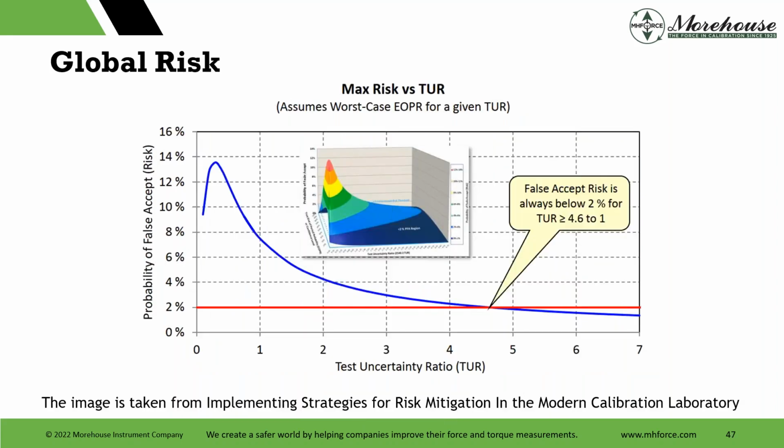And then there's another one. I love sticking this in here because everybody always harps on this 4-to-1 TUR. Its origins are from the 1950s, Jerry Hayes, Navy days. Lots of work on test accuracy ratios and some others by Wilson and Clark and some Grubbs, Kuhn, some other really awesome people in the 50s. But Jerry Hayes with the Navy really came up with the 4-to-1. They were plotting these curves, and they were thinking that they needed 3-to-1, and then they weren't comfortable enough and made it 4-to-1, and that's stuck. And there's some really good math behind it.